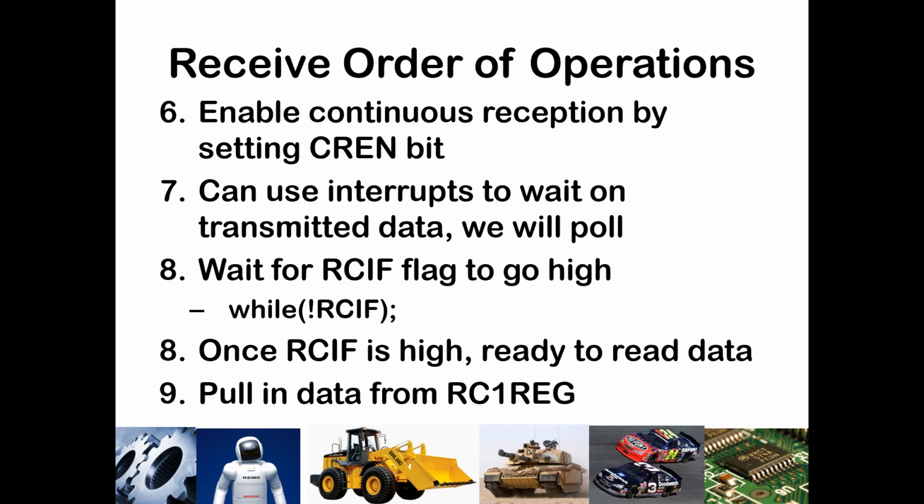So while the flag is not set, meaning the data is not there yet, we're just going to have a hard wait. So that's what the semicolon there means. It's just while that we're going to do nothing other than wait until RCIF is set. Once RCIF is set, then the data is ready and we can pull it in from the RC1REG and put it into whatever variable that we want for processing.